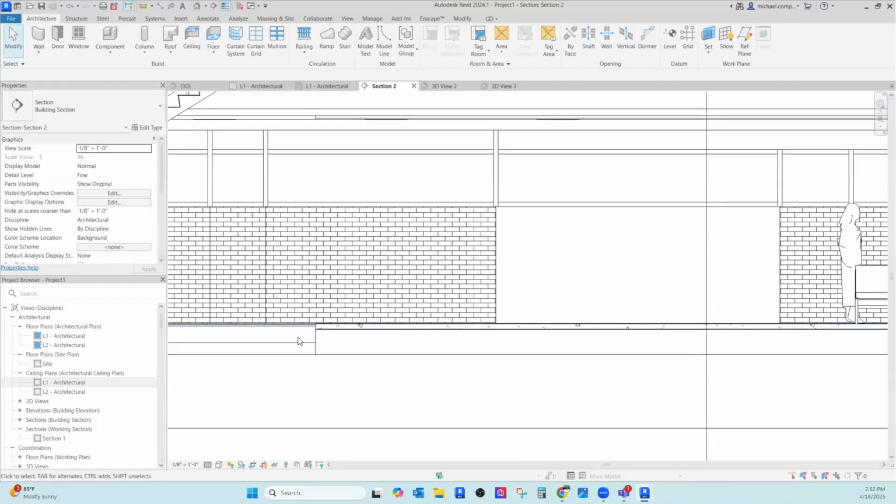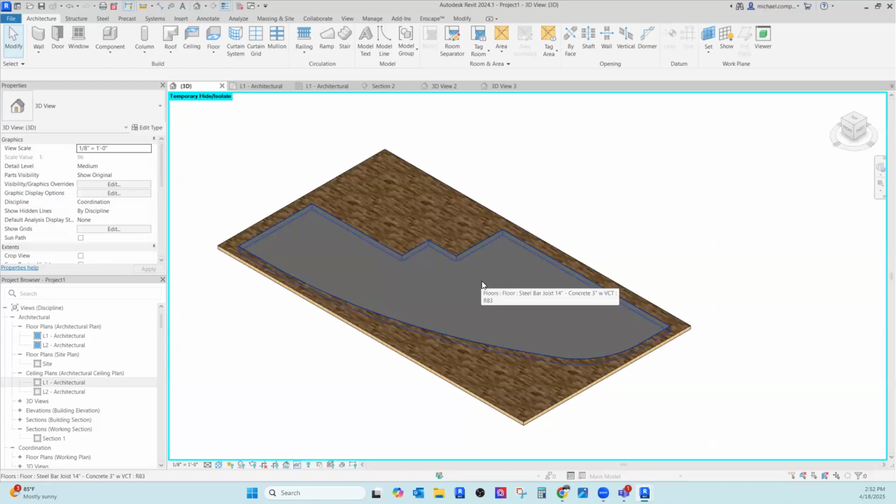You can't do that the simple way with the split face. The split face is just paint. Whereas if you're trying to change the architecture, then you have to do it this way. You have to physically model the floor separately. So there's 2 different ways of doing it. It's probably a lot more complicated than I made it, or unless I made it more complicated than it is. There's 2 ways of doing it. For our purposes, the split face should be just fine. But for the real answer is you should build them separately. Does that make sense? Yes.